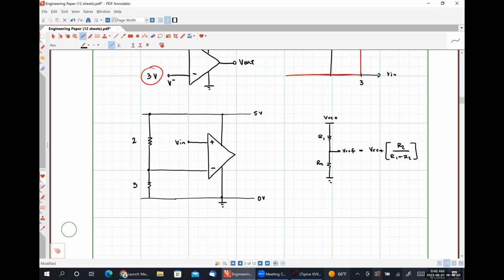Okay. So generally speaking, when we are biasing an op amp, which is exactly what we're doing here by establishing this resistor network to supply a specific voltage to one of the pins, we don't want to use single-digit ohm resistors, nor do we want to use extremely large resistors. The reason for this is, since our output resistance is usually on the order of single-digit ohms, we want our biasing resistors to be much larger than that output resistance.